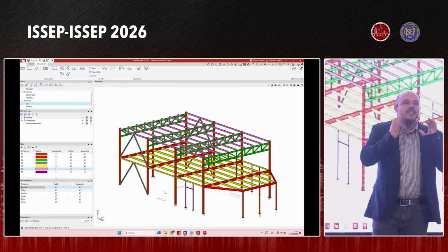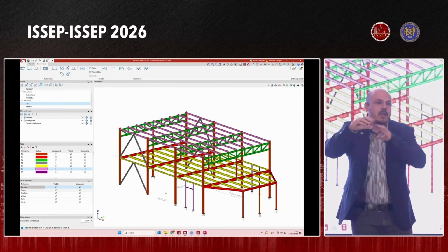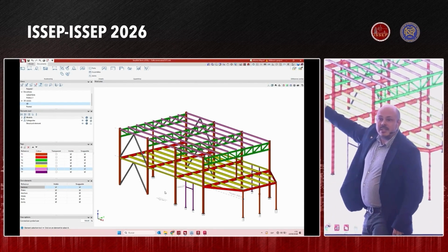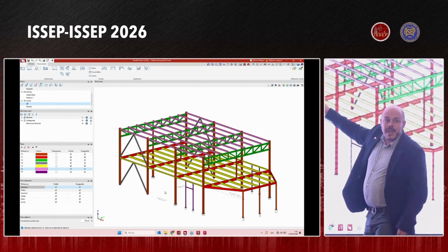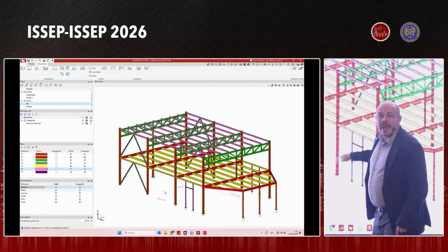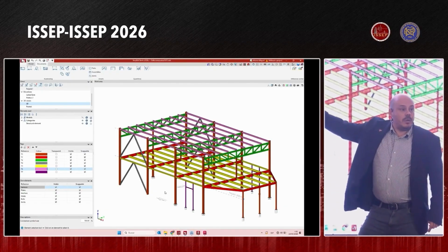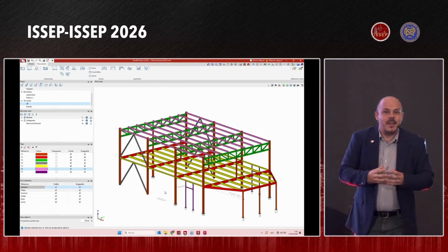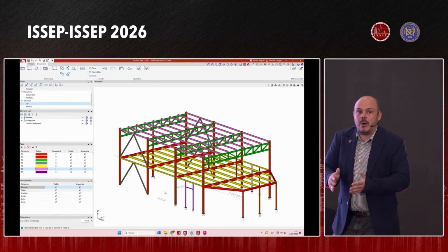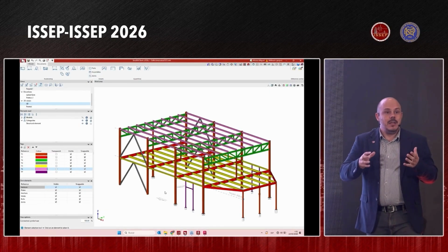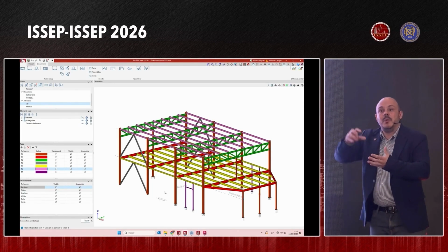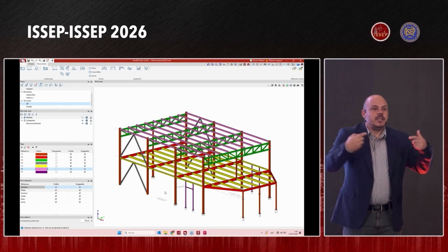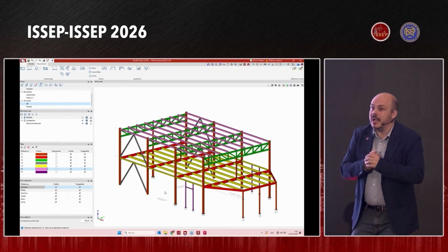This is not just 0 or 1 or a number that we can get from a bibliography. You can model this connection, you can estimate this rotational stiffness, and if you want, you can send it back to your main analysis and update your analytical model. So this is the power of Open BIM in this sense. So one thing that until now it was just drawing, it was just detailing. Now with this new information we can have a more precise coefficient for the connections, for the nodes that we have in our analytical model.